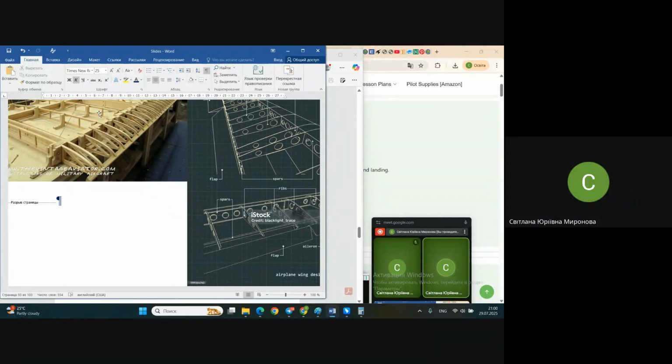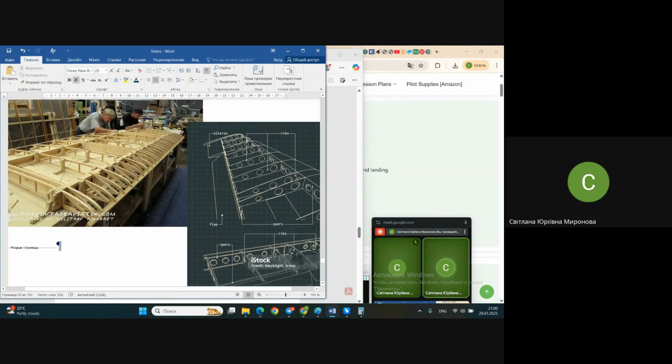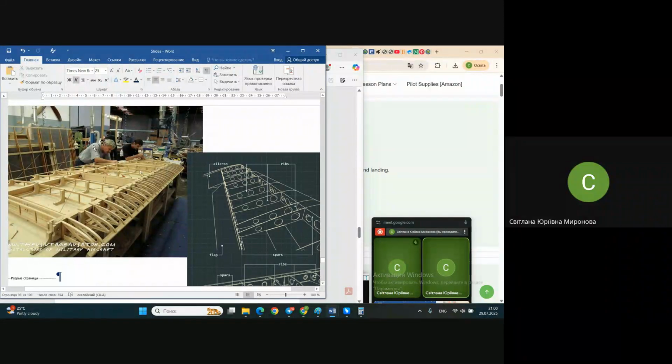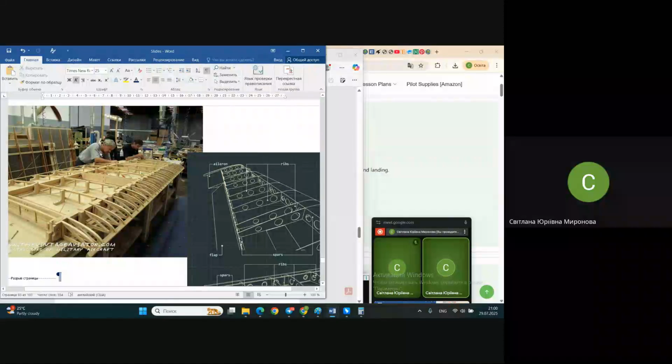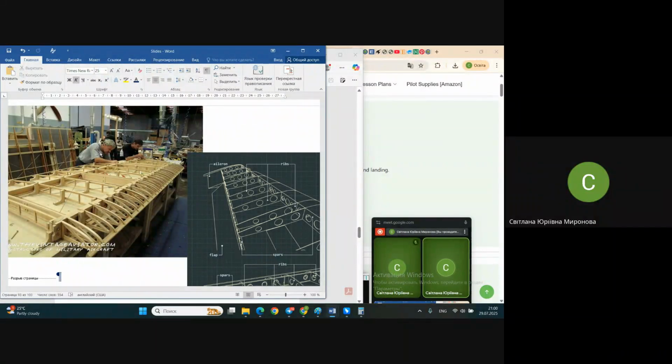So longitudinal elements are more important than transversal elements. They are working with bending moments. They are important to resist tension and compression loads on the whole structure. And torsion is taken by the structure as a whole, not by some particular element.